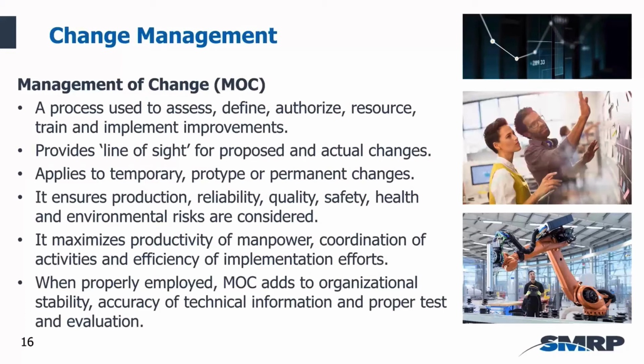A lot of times when changes happen, if we're changing an equipment configuration, for instance, or a type of material that's being used, how many times have you tried to find a drawing and found out that the drawing was not up to date, or that the documentation of how a system is assembled or some other technical aspect hasn't been done correctly? A good management of change process will make sure that whatever the changes are, those changes are not just documented into a process or procedure, but those changes are also documented in the technical information so that we can go back and check on that later.